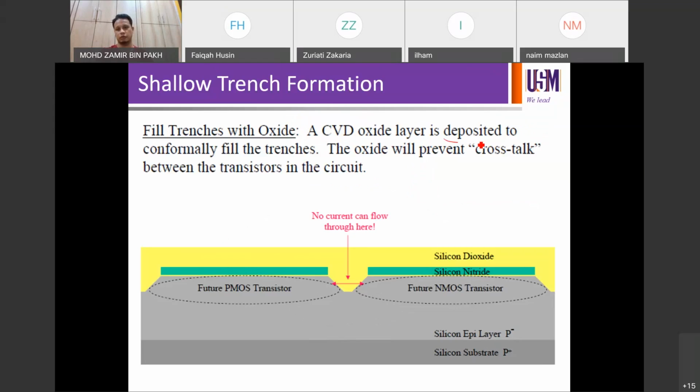Right? You can differentiate, okay? When you talk about oxide, it's either you deposit oxide by a thin film deposition process or by a growth process. Growth means thermal oxidation, thermal oxidation. Although we can call thin film deposition a growth process also, this is just to classify the two processes. So when you talk about CVD oxide, it's deposited. If it's thermal oxide, we don't call it deposited, it's grown. Right? It's not deposited. We have learned thin film deposition processes by PVD, CVD, e-beam, thermal, and multiple CVDs and stuff like that, right?